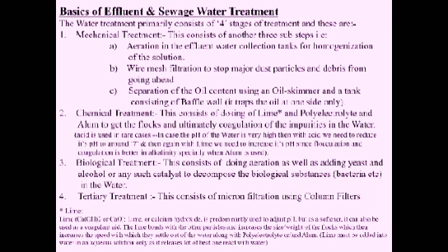It traps the oil at one side only because of the bottom baffle valve, wherein we can put the oil skimmer to get this oil out of our system. Then the second stage is the chemical treatment. This consists of dosing lime, polyelectrolyte, alum to get the flocks, and ultimately coagulation of the impurities in the water. Of course, other than these 3 major chemicals, acid can also be used in rare cases in case the pH of the water is very high.